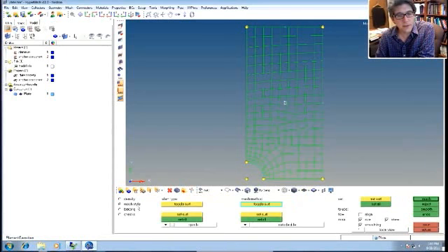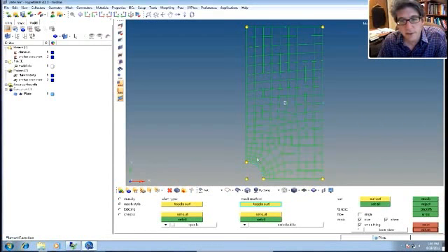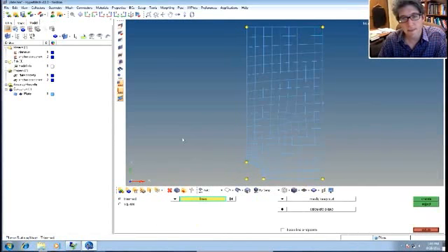It's actually quite powerful. You can also have it generate just quadrilaterals, mixed quadrilateral and triangles, or only triangles. So actually the way this is set is it's set to mixed, all right? And what it's doing is it's using quadrilaterals when it can, but sometimes the quadrilaterals will be excessively distorted, and it uses triangles to help get you a better mesh in the sense of low distortion. Okay. All right, that's good enough. I think we'll leave it at that.